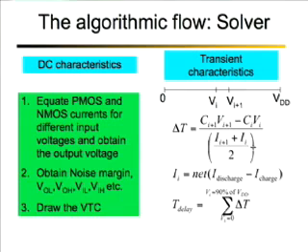Once the DC characteristic evaluation has been performed, it is prudent to go and do a transient characteristic analysis as well. One of the major differences between a traditional circuit simulator and the tool that we have developed is that we wanted to make all these estimations of delay and power in a very quick and short time. So we have done this simulation not in the time domain but rather in the voltage domain.